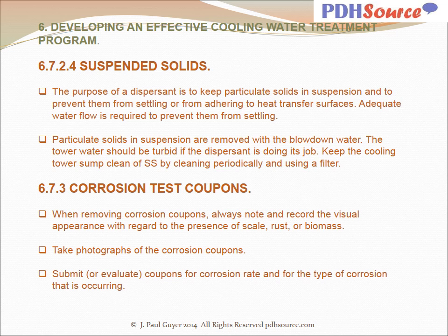When removing corrosion test coupons, always note and record the visual appearance with regard to the presence of scale, rust, or biomass. Take photographs of the corrosion coupons. Submit or evaluate coupons for corrosion rate and for the type of corrosion that is occurring.